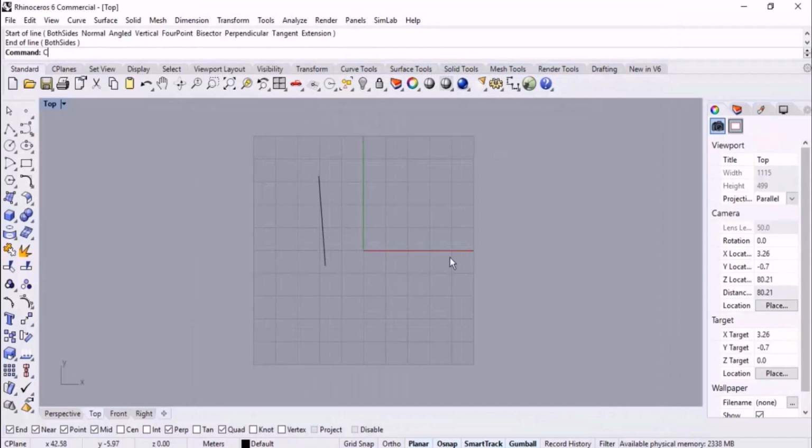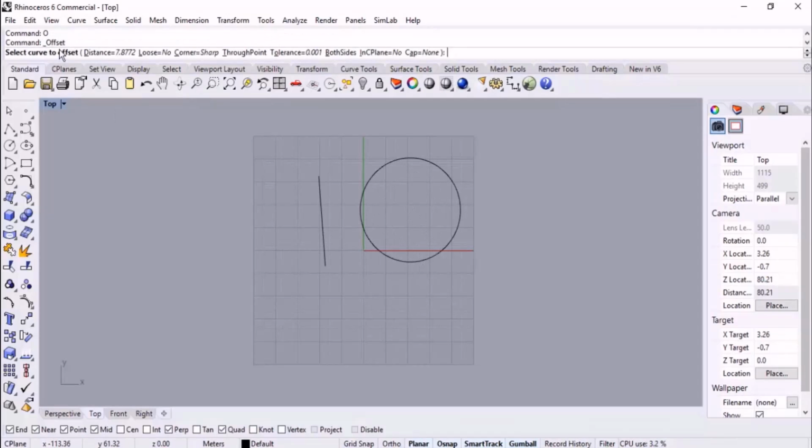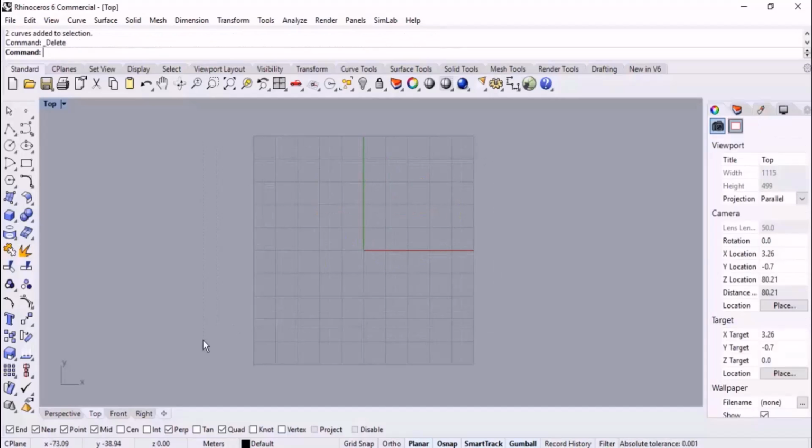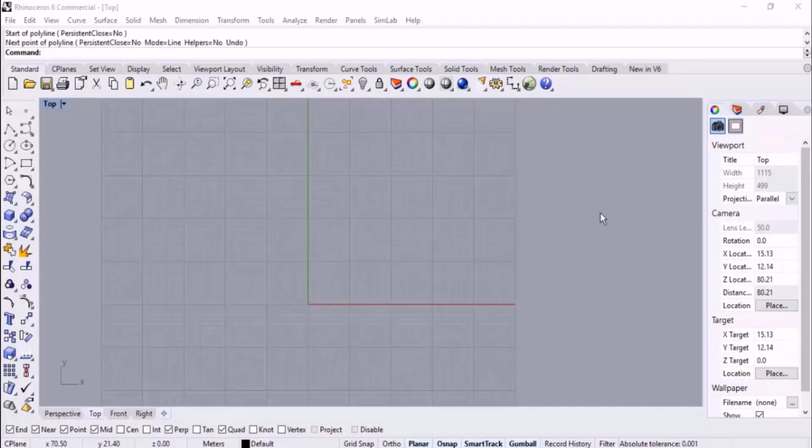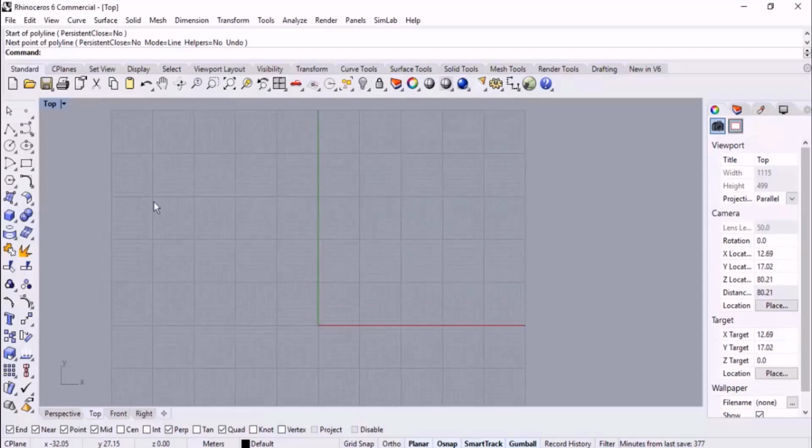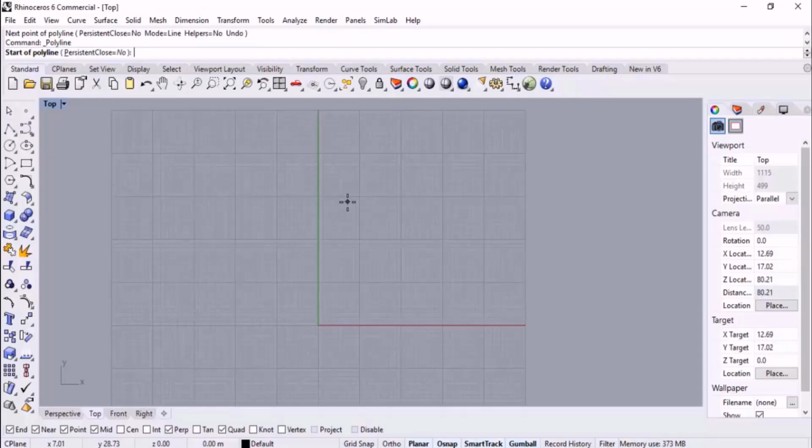Okay, so if I type L in the command line, we will be provided with line, or C circle, O offset. Well done. So in this way we will have some background about Rhino. So it enhances your self-confidence, since you already master parts of the commands in Rhino. The first drawing command that we're gonna cover is line. Polyline. I click on it to start the command.